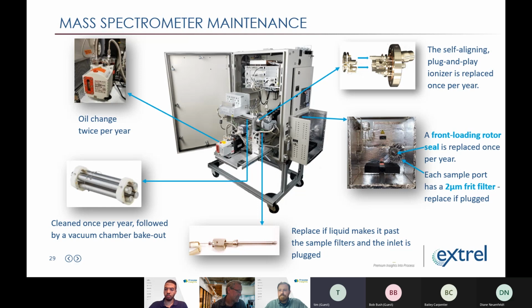So what we did is we used the Rosemount conditioning orifice plate with the mass flow transmitter, which has pressure, temperature, and differential inputs. Based on their analysis, I think it's 22-to-1 turn down, which met the 5% just barely that the government specified for the project.